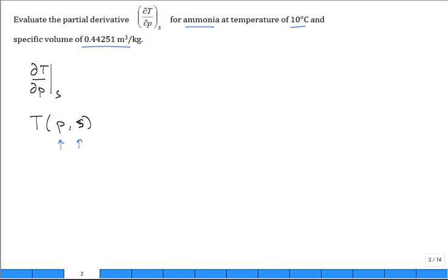properties like temperature. When you approximate this derivative numerically, think about you need a temperature 2 minus temperature 1. A temperature difference divided by a pressure difference. Isn't that the general formula for df/dx or dy/dx or d-something/dt? You know, the change in the numerator over the change in the denominator. This temperature, just think, is a function of pressure and entropy. So it's a function of, let's say, some pressure and entropy.